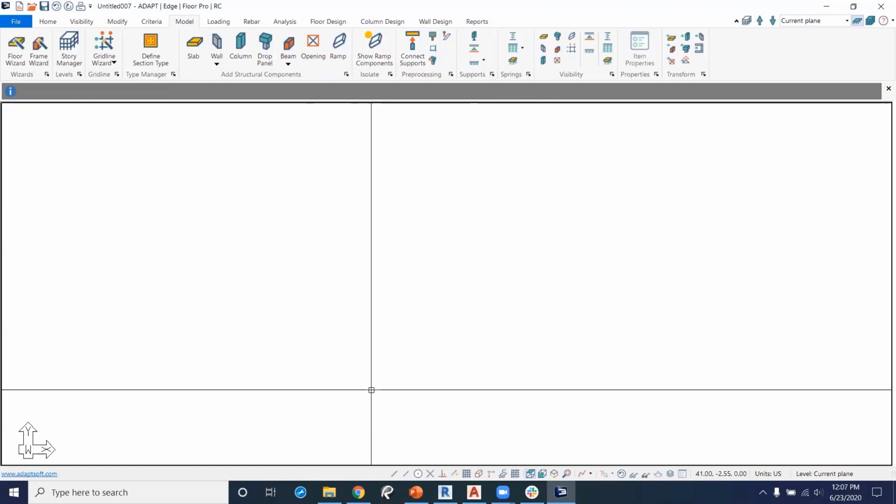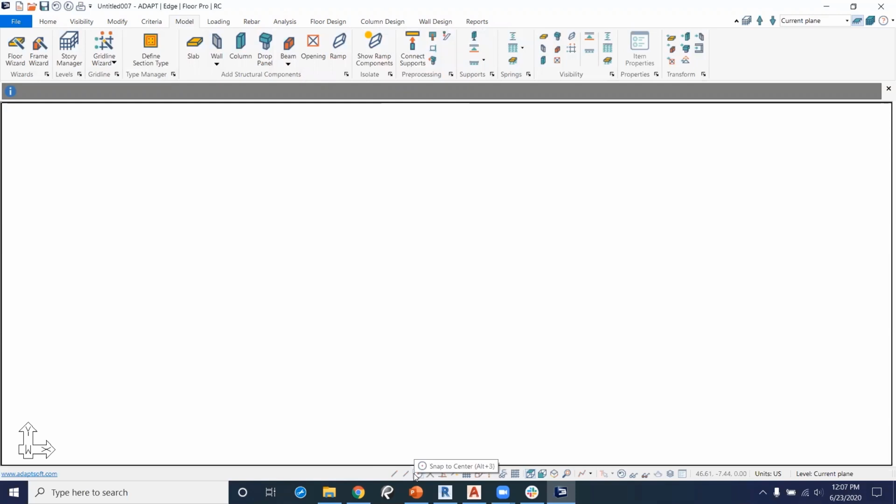At the bottom, we have our quick access toolbar, which has features that are commonly used, such as snap tools, views, and component visibility. One thing I love about Builder is you're actually able to create your own custom hotkeys. For example, I have my snap tools hotkeyed to Alt-1, Alt-2, and so on and so forth. This helps speed up your modeling process without you having to learn hard-coded shortcuts. You can customize them to your needs and in a way that you'll remember.